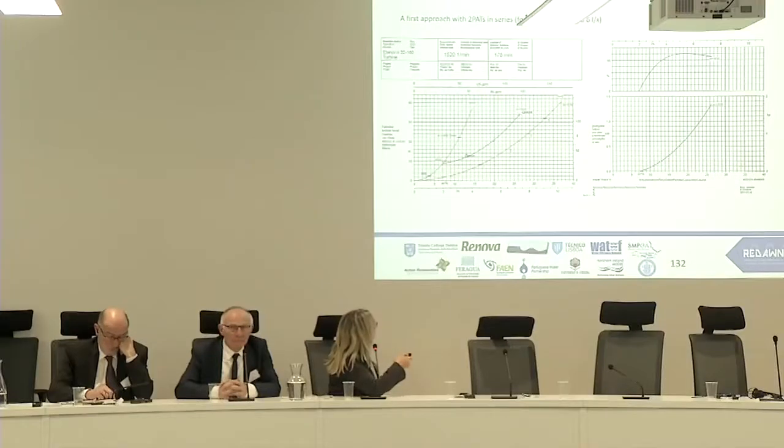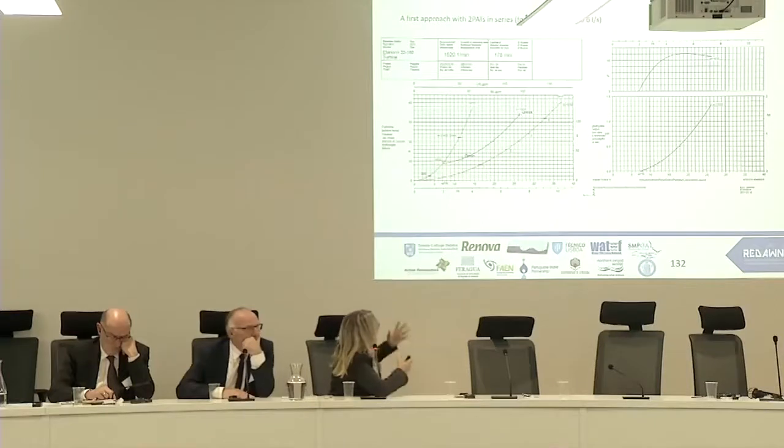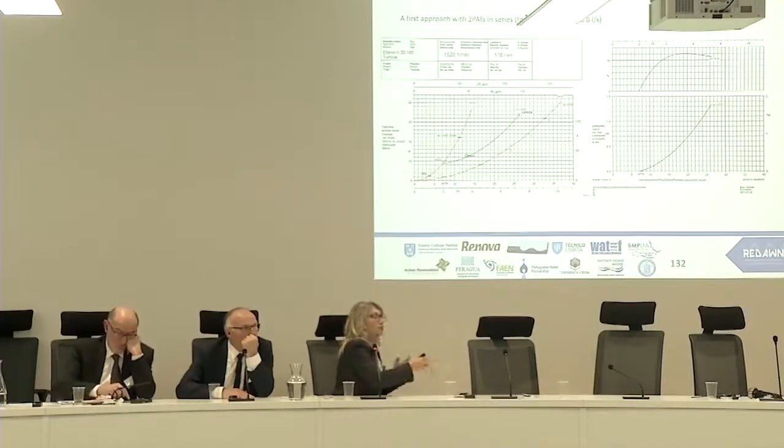For example, in this case, since the flow is quite small and the available head is high or medium, around 70 meters, we could use, looking at the availability, a pump working as a turbine. Maybe it is necessary to consider a multi-stage, multicellular pump, or 2 pumps in series, etc. We need to analyze the different possibilities in order to optimize the energy production.